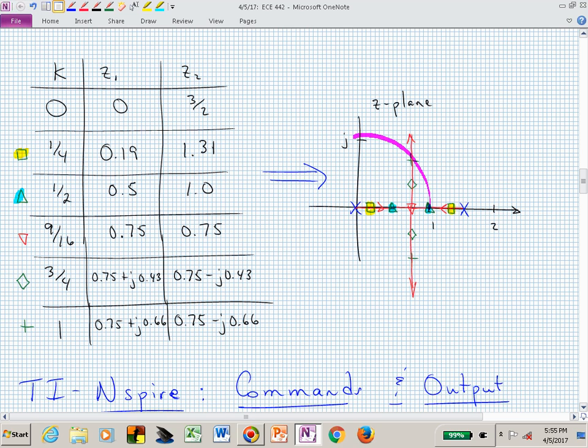there's a quarter of the unit circle. Now what we're trying to do, and maybe to emphasize it, I would do this. But do we initially start with the branches, or if the system is stable, then we need all of our closed loop poles to simultaneously be inside the unit circle. In this case, how many poles do we have? Two. We have two closed loop poles. Do they initially start both in the unit circle? No. So we know that at k equals 0, that's not in our range of stability.